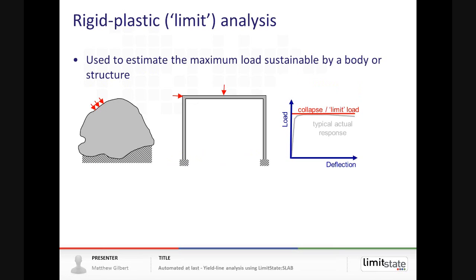For those of you not familiar with rigid plastic or limit analysis, generally speaking, it makes an assumption about the mode of response of the material. It says basically that you can ignore elastic deformations, and you can assume that the failure takes place in a ductile manner, so you have effectively a rigid plastic response as shown on the load deflection graph on the right.